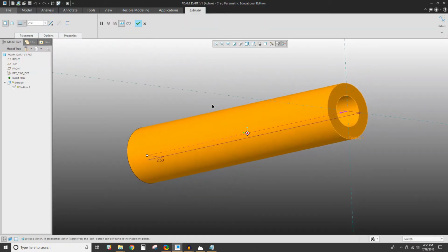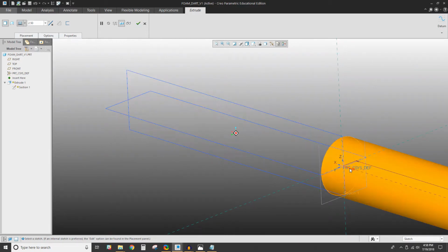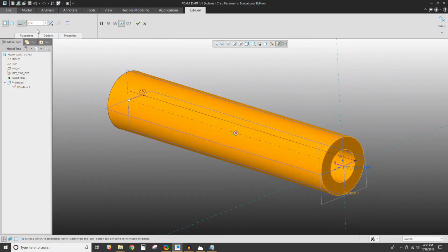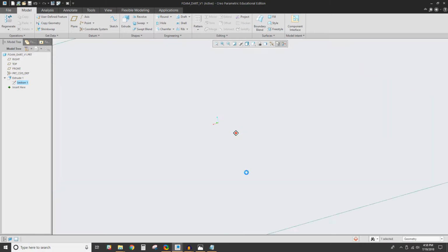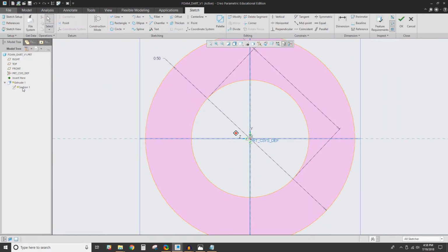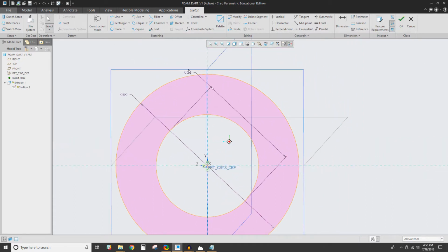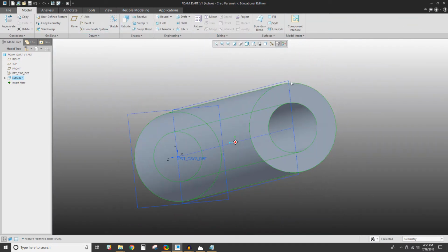So now you can edit the height of your extrusion and the direction of it by clicking on these arrows. Or if your dart was too big, like I mentioned earlier, just click on section 1 and click edit. In the same fashion, it will bring you to section 1, which is what this sketch is called. Your dimensions should look like so. Click check.